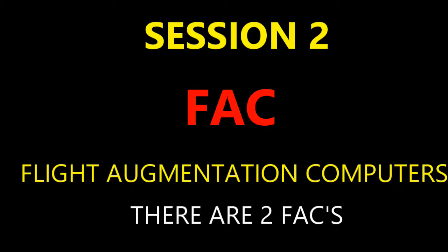Now, how do you test the system? How do you test the wind shear warning system? There's a test for this, and what it's doing is checking to make sure that the system will indeed display visually, or provide that audio warning of the wind shear when it's present. Okay, and messages are there to indicate the loss of that. So that's all performed through the CFDS, through the MCDUs. It's kind of the same as what we've seen with other systems, but it's going to say system report test. So you just run that test.